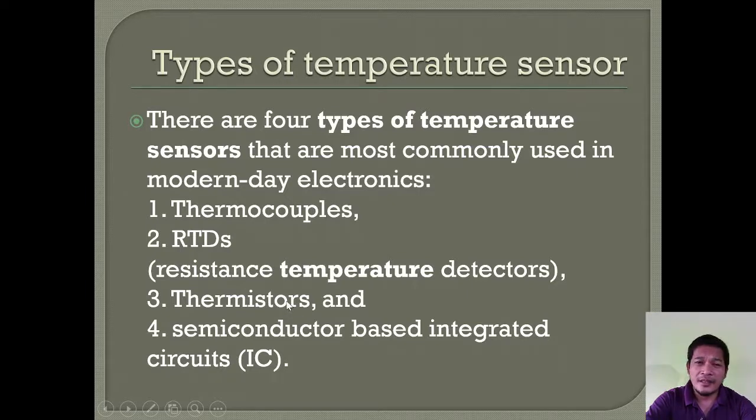As mentioned with the stove, temperature sensors usually give a voltage as output. With thermistors, the supply voltage is placed in series with the thermistor, making it a voltage divider. Whatever the resistance changes, the voltage entering your processor changes. As we discussed in EST 201, the Arduino board's A0 input pins can only accept voltage from 0 to 5 volts.